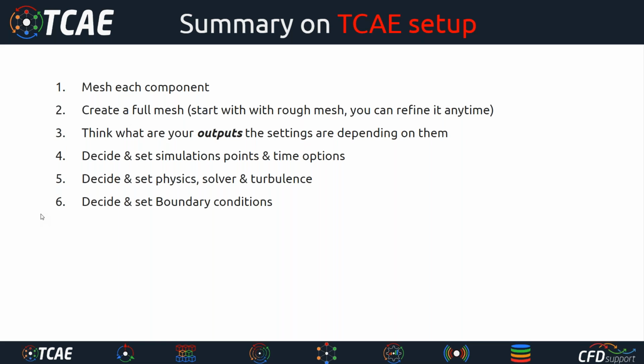Boundary conditions define all your workflow, and if they define the whole case and everything, they are extremely critically important. So, boundary conditions. Then you definitely need to decide how to visualize during the setup. You already should know what the outputs are and how to preset the post processing, because a lot of things are happening during the simulation, and you cannot change it when it's done.